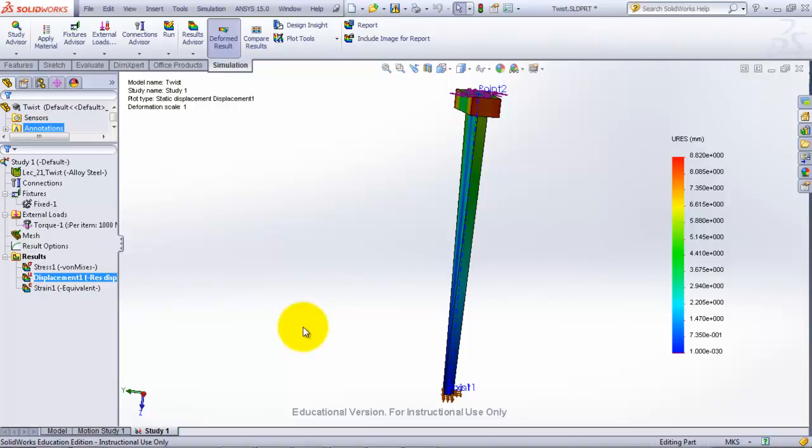So remember the 8.82. This is the part of the verification. When we verify our mesh, we want to make sure that it's sufficient, that if we get a finer mesh, we don't see our results change. That's the key aspect to verifying our mesh.